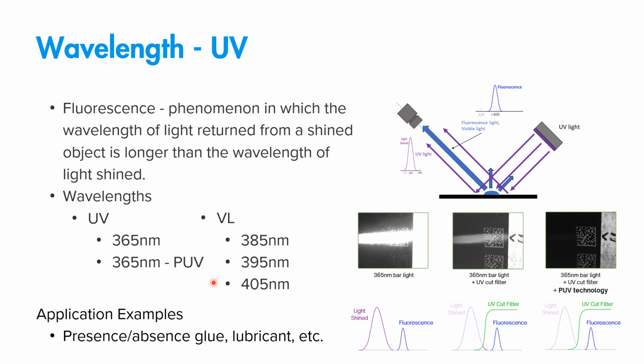Pure UV will not hurt any application that you're solving, even if the application doesn't require it, even if it's not a high glare application and you just need a UV light. It's still 365 nanometers, so it's still going to fluoresce or not fluoresce the material that you're testing. But it will only help if you are testing a highly reflective sample. So for your lab, I would say 365 nanometers in the pure UV. And once again, same as IR, the form factor doesn't matter much because you're just seeing, does this fluoresce or does it not? They actually don't even make UV light in that many different form factors.